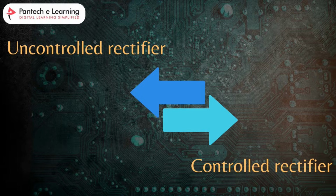Here the output voltage and output current can be adjusted by varying the firing angle. So what does firing angle mean? It is the point in the AC cycle when the thyristor starts conducting. That is the firing angle. This provides greater flexibility in controlling the power that is delivered to the load.